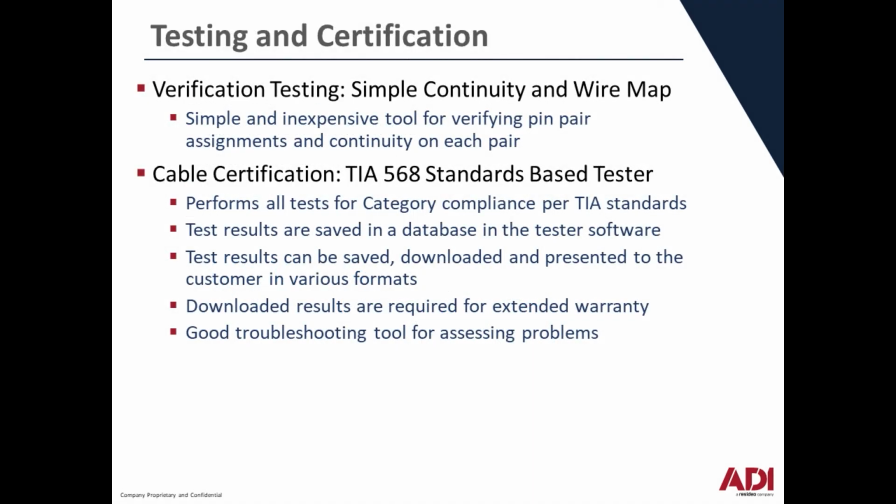An important component to any cable installation is testing and certification. The key factor in selecting a tester is understanding the need for verification or certification. A verification tester merely verifies that the cable is connected properly. Choosing a certification tester guarantees the cable system is in compliance with industry standards. These testers also provide test results that can be saved, downloaded, and presented to the customer. Most cable certifiers also offer troubleshooting tools to assess problems within the installation.